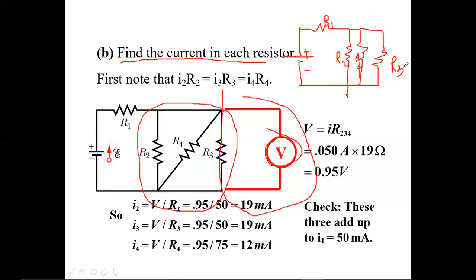For that, is nodal analysis better? No, right? Here the node is common for these three resistors, so nodal is not good. Is mesh analysis better? For this, I need to apply three meshes, which is a lengthy process. Then, does it come under the star or delta category? No, right? So there is only one way we can solve this problem, only in series and parallel mode. For that, you need clarity about which technique we are going to apply.